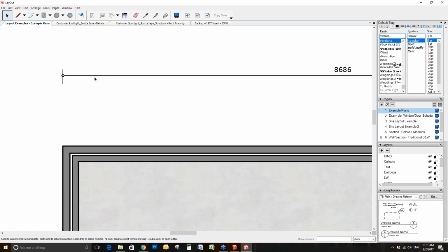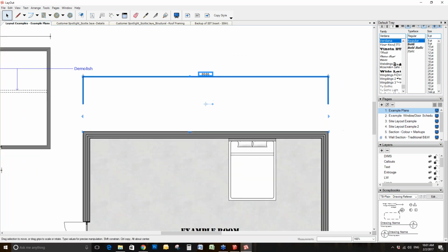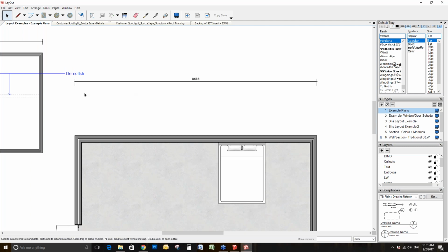You can't set it up, and obviously if you move it out, it's going to pick up where you first started to draw from. To manipulate this, all you need to do is double click on the dimension line and then change the leader itself. Once you've done it, you can simply reference it. We will be releasing a template for Australian users that want to do it in this way, that will automatically do it for you, so that will be released shortly.